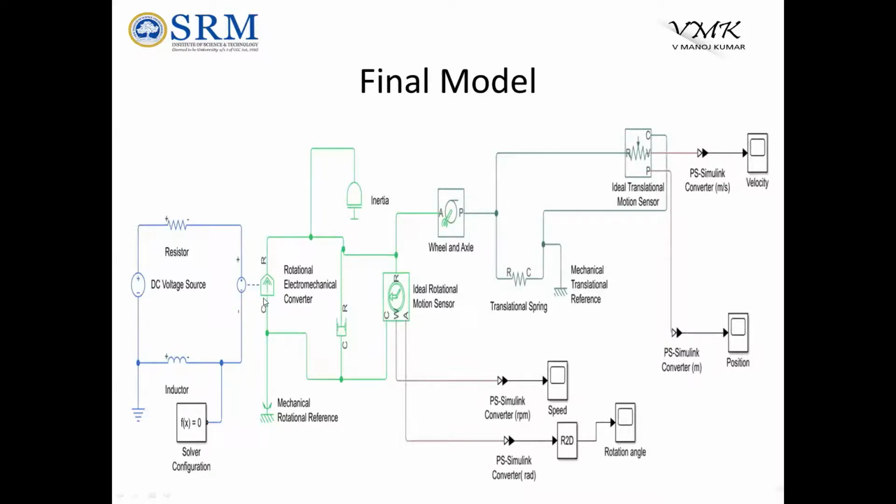This motor needs some housing. The motor cannot just sit there; I need some nut and bolt to tighten the motor so that vibration can be arrested. It's a housing, nothing but a frame given to my motor such that the motor is fixed to one point. If I did not fix my fan to the wall, it would vibrate. So the housing frame is the mechanical rotational reference.